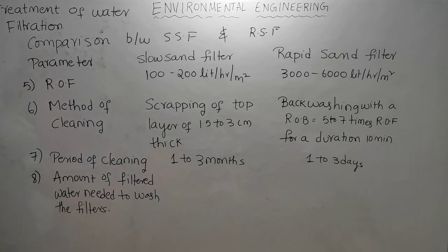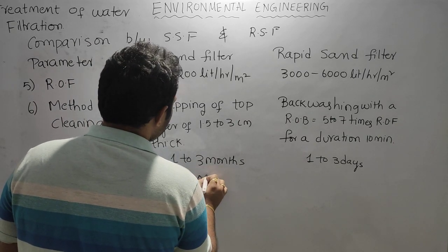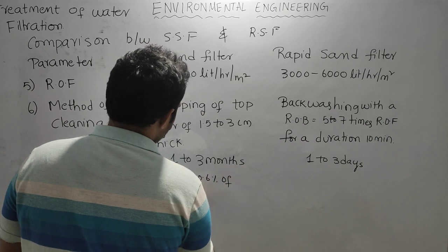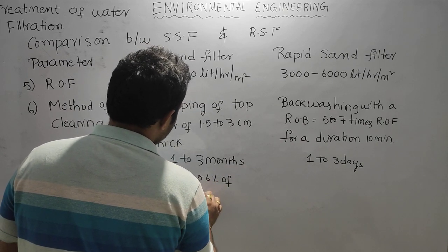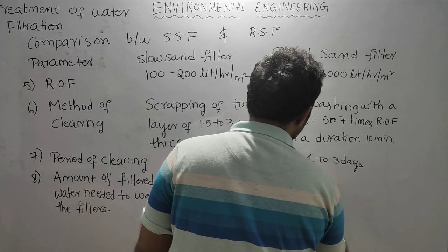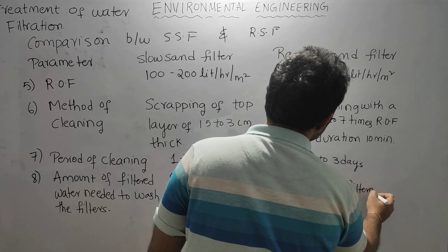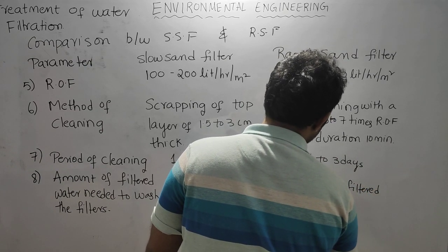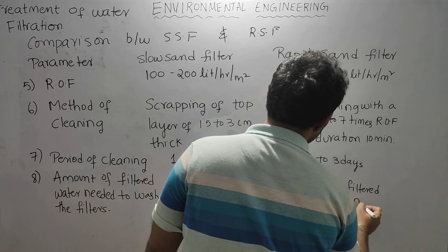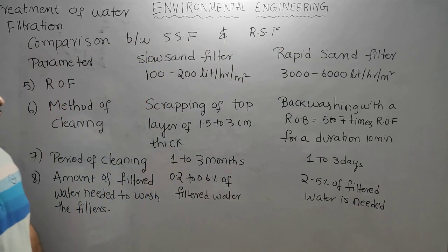Here it is 0.2 to 0.6 percent of filtered water. Here 2 to 5 percent of filtered water is needed for cleaning. So these are the important comparisons.